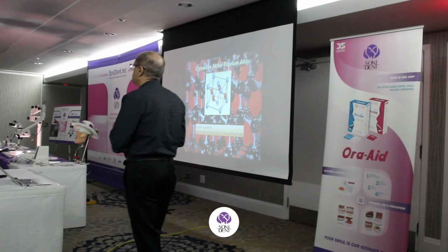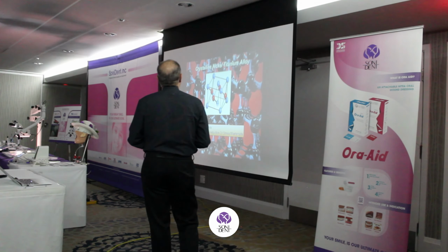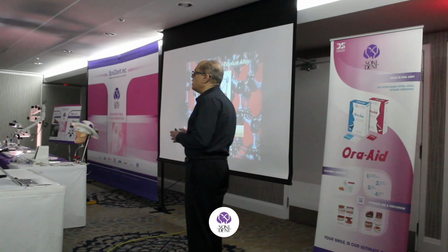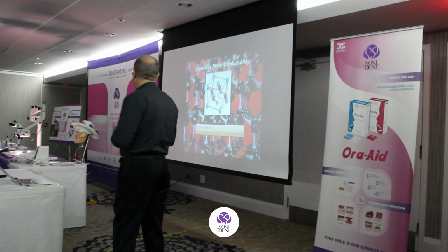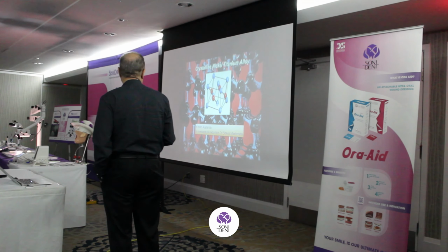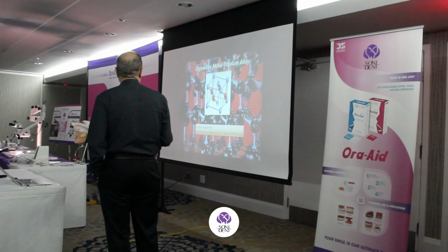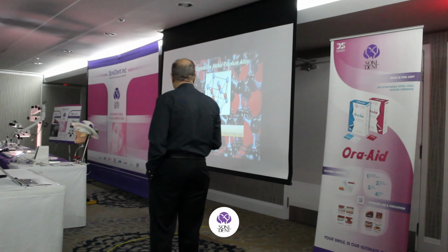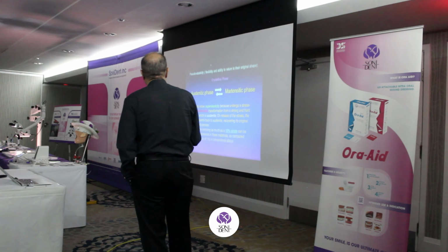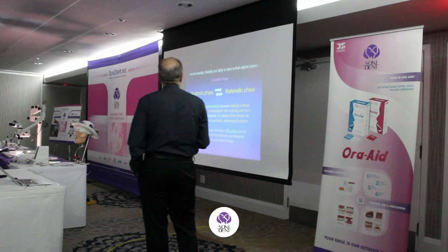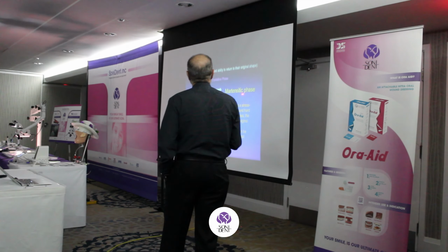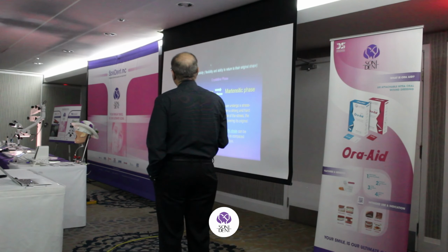So why is this crystalline nickel titanium alloy flexible? It's because it has two main phases and it can transform. So in the rest situation, it is in the austenite phase, and under temperature reduction and stress, it goes to martensite. This transformation from the austenite phase to the martensite phase causes the pseudo-elasticity.